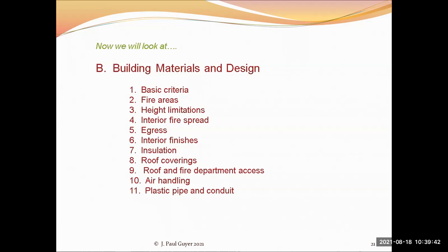Now, interior finishes are important in fire protection because of the issue of flammability and smoke generation. And some of the materials that have been used in building construction in the past were pretty flammable. Some of the insulations, this sort of thing, things like drapes hanging on the walls, perhaps as a decorative feature. They're flammable and they generate smoke. And again, the smoke, of course, is a big hazard to the occupants.